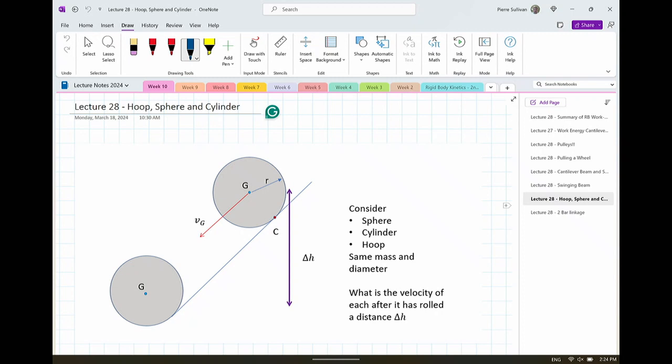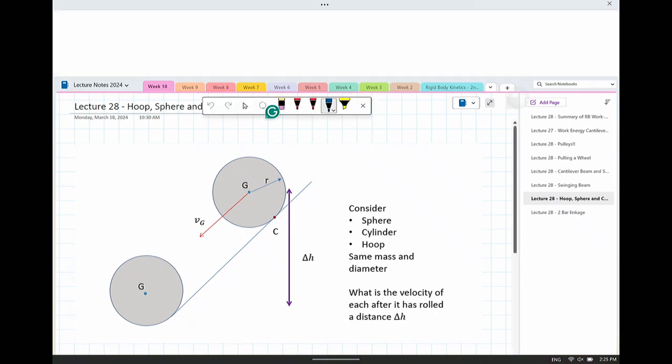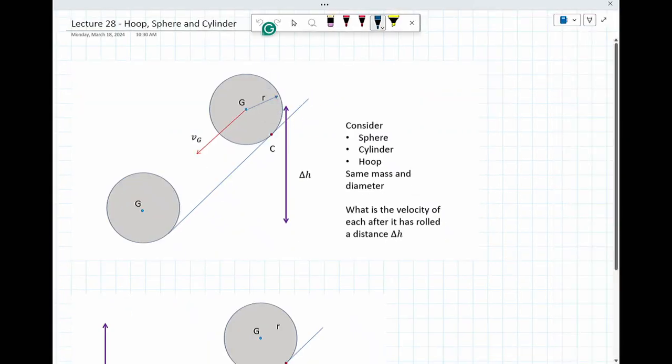And it goes to a question again. One of the values of Piazza for me has been that I can have a sense of what's going on sometimes with material. And one of the things that has been really important is wrapping your head around moments of inertia. Moments of inertia really are just a replacement for mass in a moment equation. So you have a second law term that looks like a mass, and that's all you got to worry about.